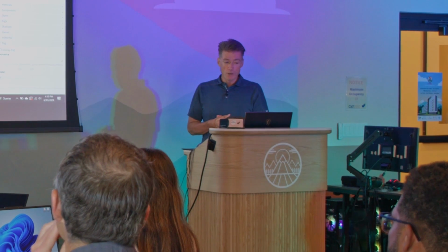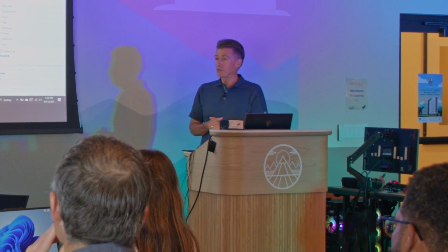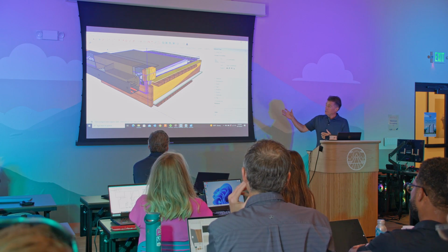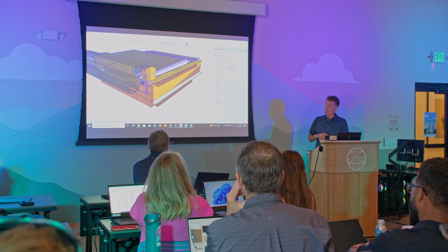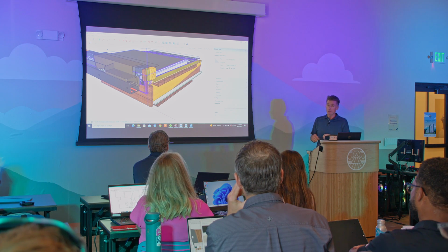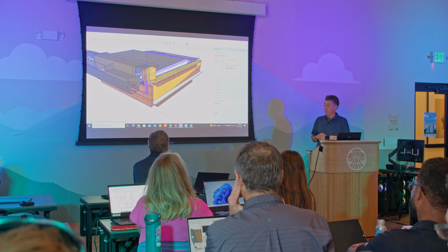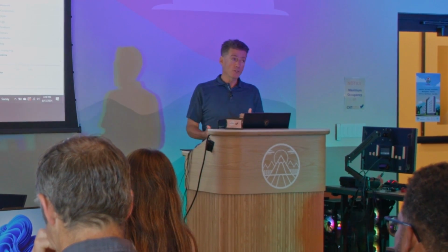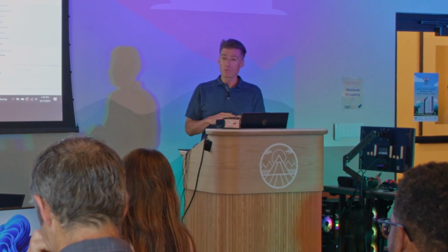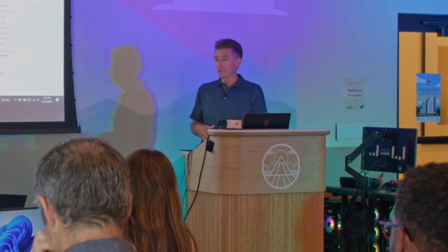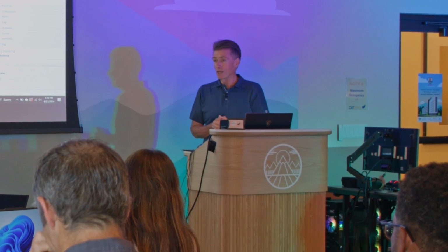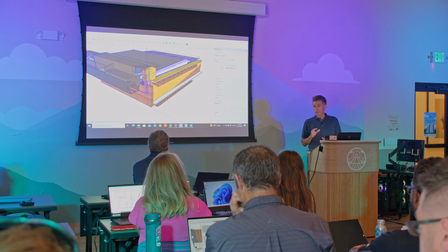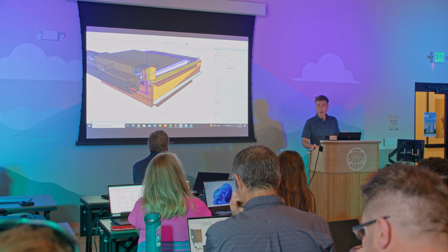So it will cover not only timber framing, but it would also have a framed condition where we have, as you can see here, decking underneath with, and we're required to do this for fire, 5/8 exterior type X gyp sheathing underneath, and that's to protect for fire. If we have an assembly that's timber frame with 2x decking, we're not required to do that because those meet the requirements, at least the old requirements, for calculating for a 1-hour assembly, as long as you have more than 4 inches of width and 8 inches of height, nominal.